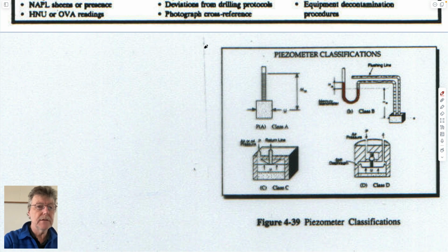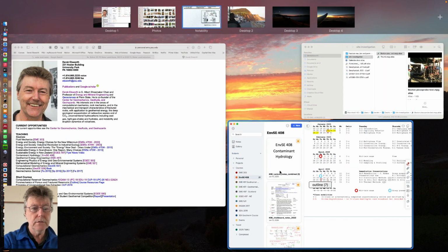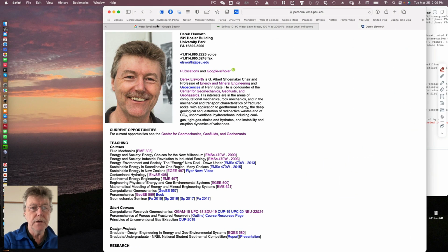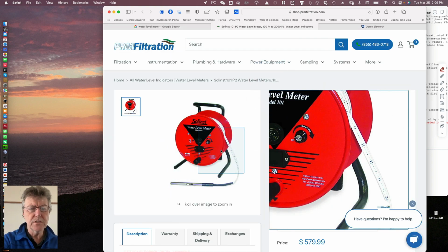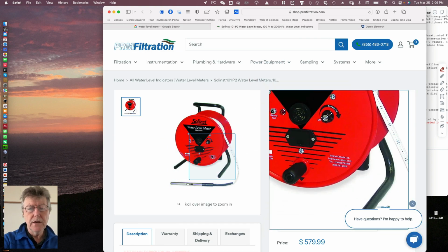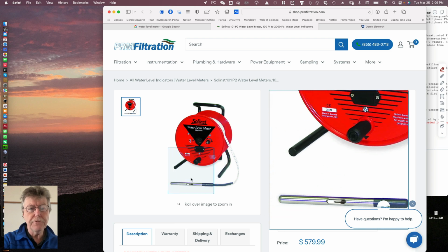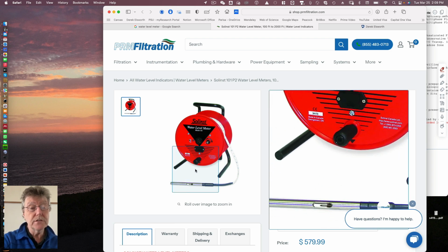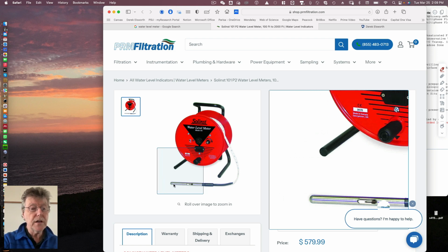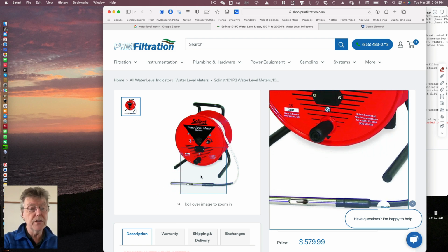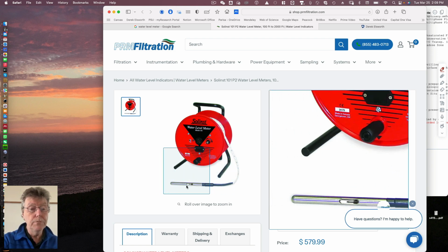I guess I had that as well. Water sampling. I think we looked at this before. These are water meters, it's pretty straightforward. To measure water levels, if you have a piezometer tube, you can directly measure the water levels just by lowering this down into the hole.